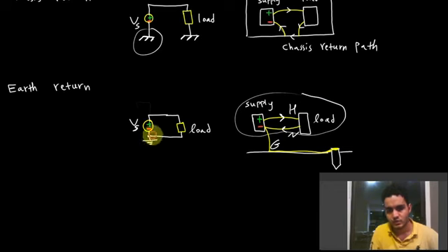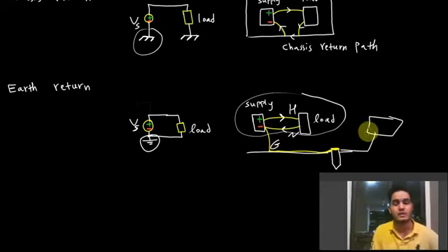But then what you want to do is just add this symbol here. What you're doing here is making it so that the negative terminal is sitting at 0 volts, so it would be common with other electrical devices. They would all have the same reference. And typically you have very low resistance wires connecting the ground connection to the prong that is ground, to the breaker box, and to the ground rod. Because of that, there's very, very small parasitic drop across the resistances there.